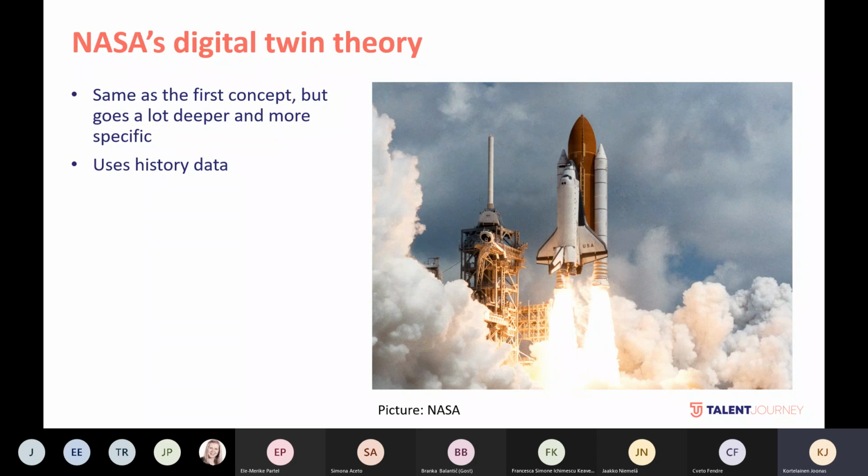And the twin is described as an ultra-realistic one and may also include one or more important and interdependent vehicle systems, including propulsion or energy storage, avionics, life support, vehicle structure, thermal management, and so on. In addition to those physical models, the digital twin integrates the sensor data from the vehicle's onboard integrated vehicle health management system, its maintenance history, and all the available historical and fleet data obtained using data mining and text mining.